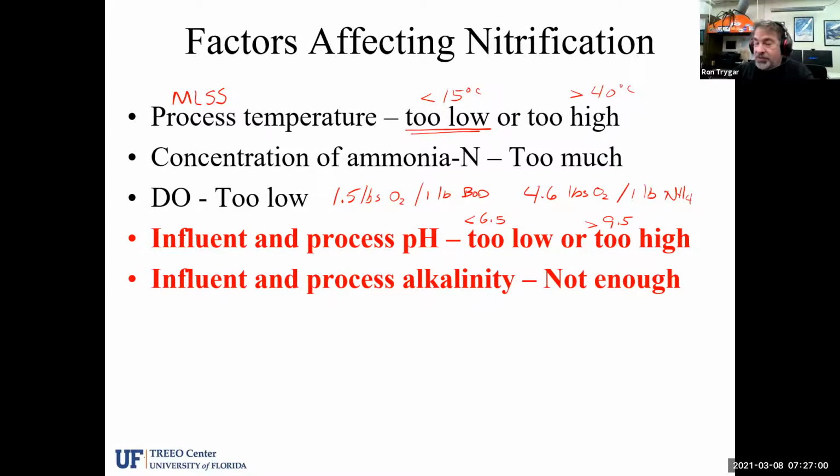A chemical source in this case would be ammonia or ammonium, and they make the energy from that, but also they consume carbon from the carbonate alkalinity coming in, or bicarbonate alkalinity. So their diets are a little specialized as compared to some other bacteria. Autotrophic bacteria have more specialized needs for forms of carbon and energy. So they get that from the ammonia and the bicarbonate alkalinity.